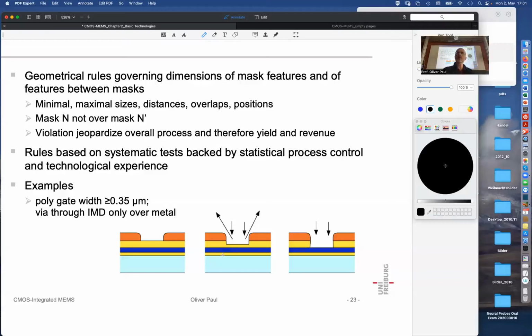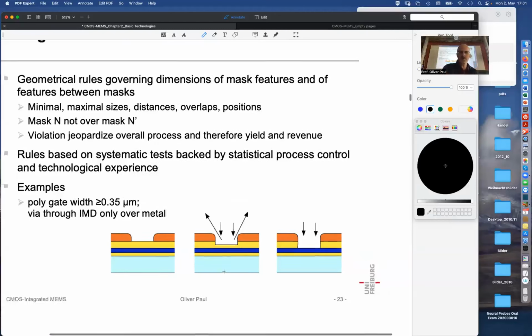Maybe I missed a spot, and then he's on the safe side. If that etching doesn't stop, he will continue, through the field oxide into the silicon, and then the etching is completed, because then the color will again change. But the distance may have been too far. So these are typical design rules that you find.